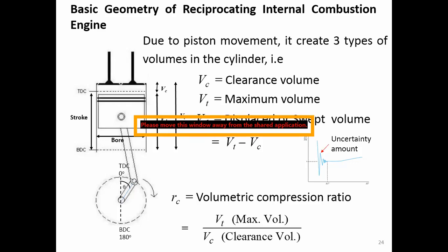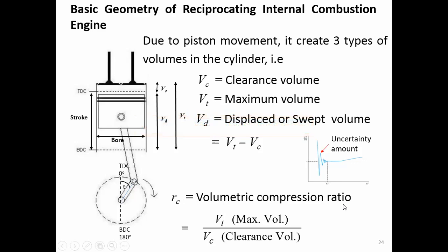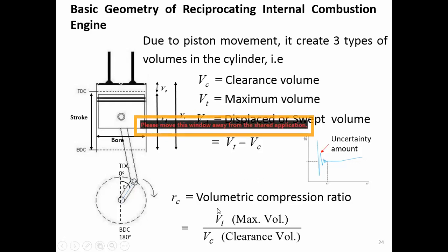But it is not. So remember, in the internal combustion engine, when we talk about the compression ratio or volumetric compression ratio, it is always the ratio of the volumes, not the pressures.